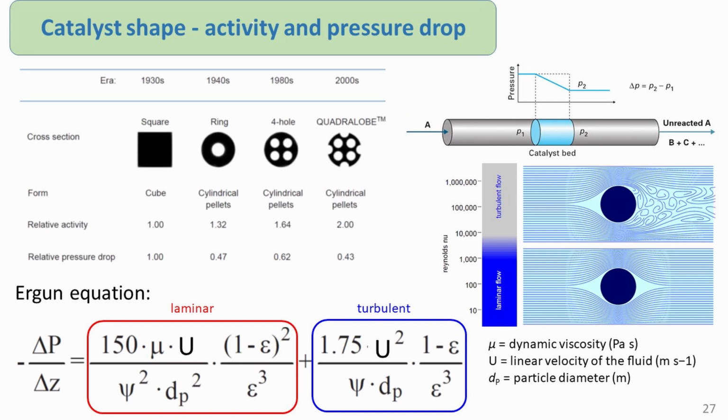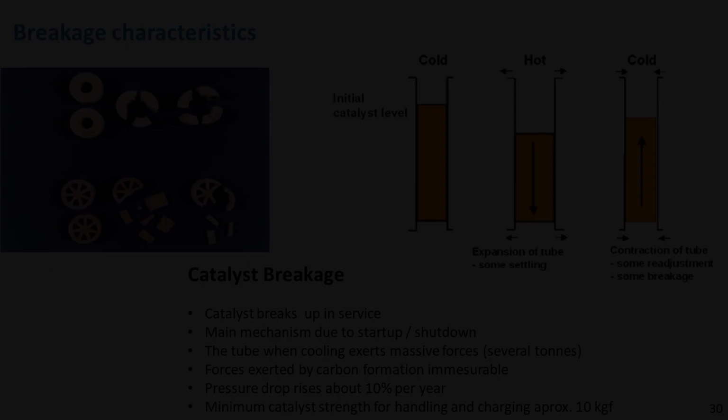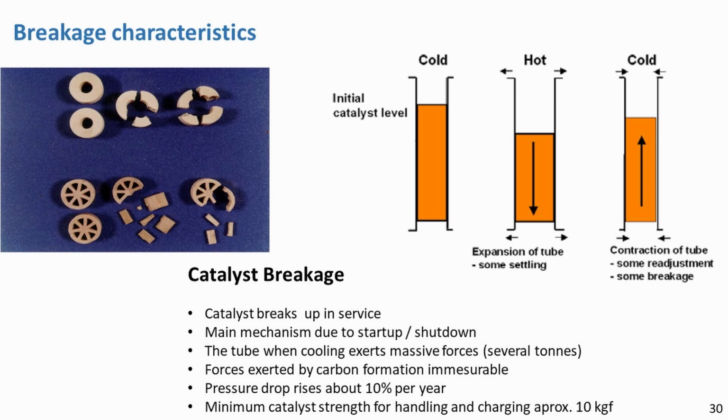The catalyst should be mechanically stable under all process conditions as well as during startup and shutdown of the reformer. In particular, resistance to conditions during upsets may become critical. Breakdown of catalyst pellets may cause a partial or total blockage of some tubes, resulting in hotspots, hot bands, or total hot tubes. The formation of carbon may result in the same problems.